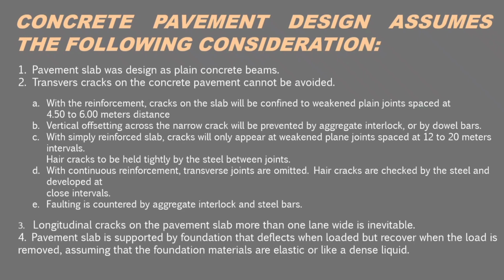And 3. Longitudinal cracks on a pavement slab more than 1 lane wide are inevitable. That is, the pavement slab is supported by a foundation that deflects when loaded but recovers when the load is removed, assuming that the foundation materials are elastic or like a dense liquid.